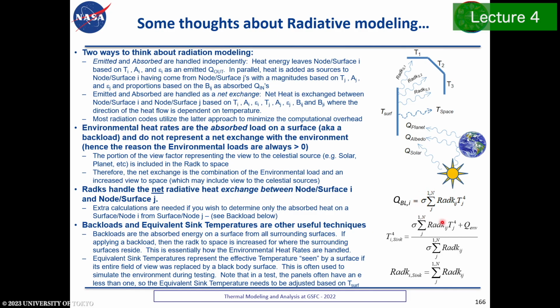This backload term is good if I need to represent, well, what's the heat from my spacecraft onto your instrument, so I can provide you a loading so that you can do your design and say, well, you could expect that I'm going to be giving you 15 watts of energy from all the things around you, from me radiating to you. And similarly, we can boil this down further to an effective sink temperature, which is really what we do for thermal testing.